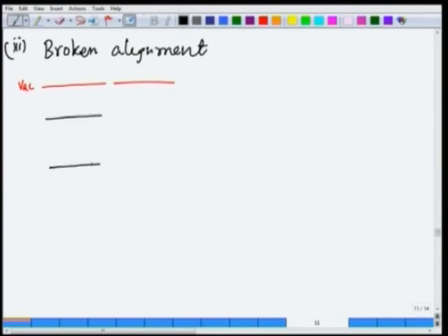this is one semiconductor, and the other semiconductor is actually even below this. So this is EC2, this is EV2, and this is EV1, and this is EC1. And what we are going to do is join them here, somewhere here. Unfortunately, in this case, the EC2 level is even below the EV1 level, and hence it is called broken alignment.